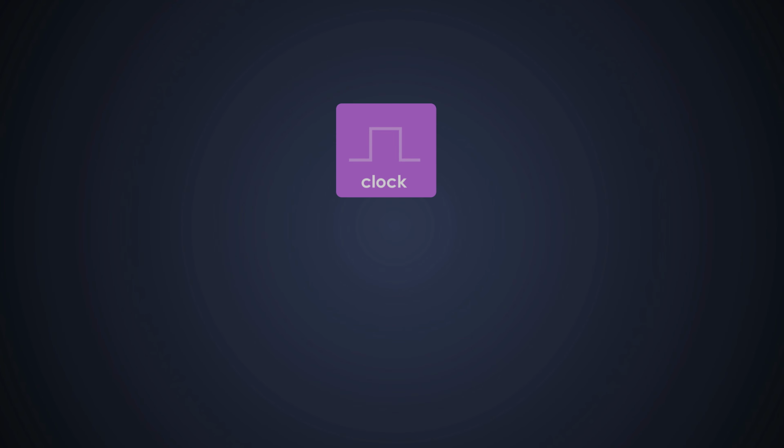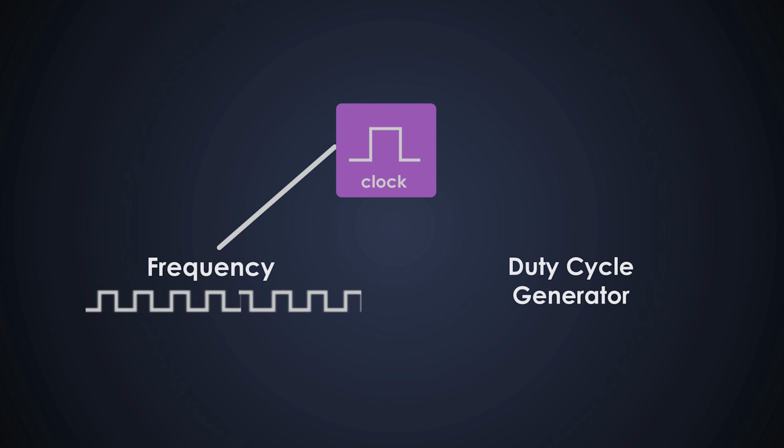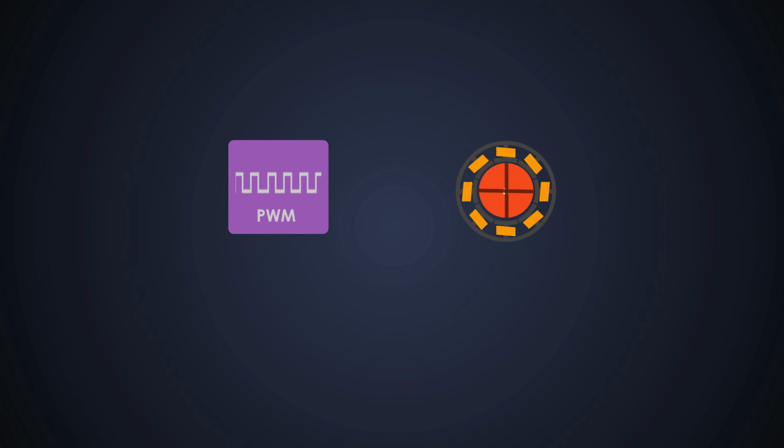The clock is basically a frequency and duty cycle generator. It has a 4 MHz crystal oscillator. This block gives us variable duty cycle which can be controlled by using the switches. Now the PWM section controls the dead time function and enables PWM. Well, the direction of the motor is also taken care of by this block.